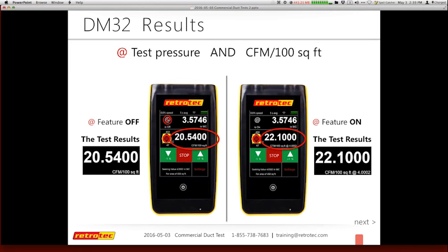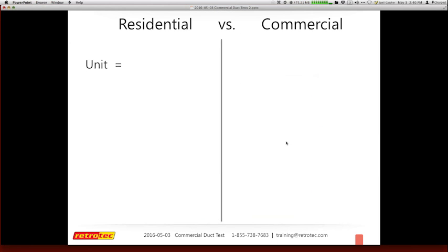It doesn't include the VAV valves, or the variable air volume units that may be secondary conditioning. So the commercial concept is completely different from the residential concept of testing everything at once. There are separate SMACNA standards on how to test the air handler by itself, so that it's always isolated as a test, and we're only testing the main duct systems by themselves.